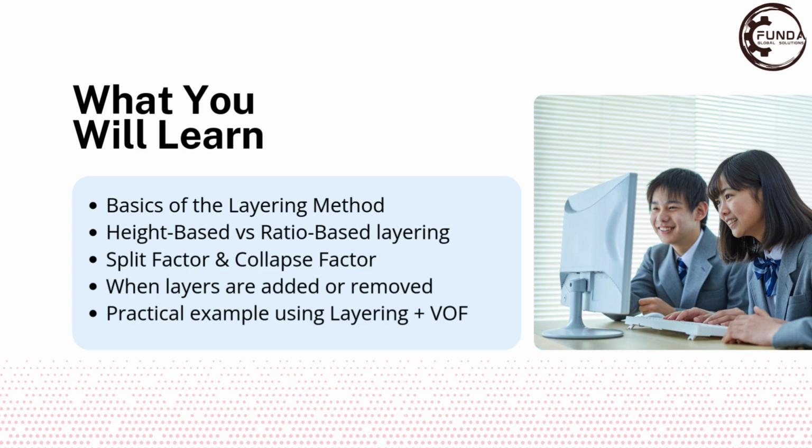In this lesson, you will learn how the layering method works inside the Dynamic Mesh framework. We'll understand its two modes, height-based and ratio-based, explore split and collapse factors, and finally walk through a real-world application on a wave generator using Dynamic Mesh plus VOF.